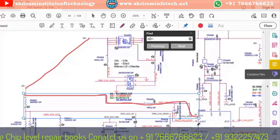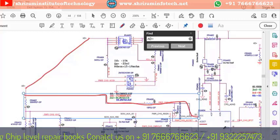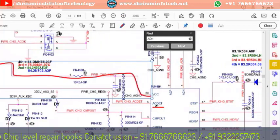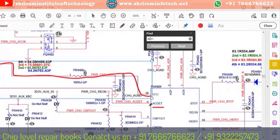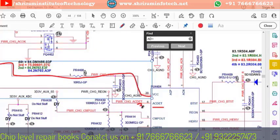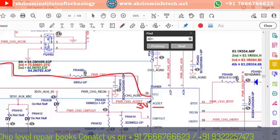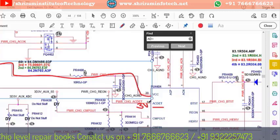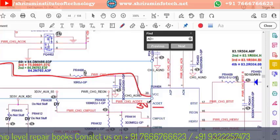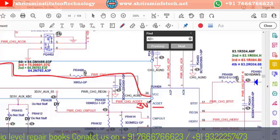Then there is one more pin which is also very important, that is called AC detect. AC detect means adapter current detect. You should get 3 volts here at pin number 6. If 3 volts is coming, that means the adapter is detected, the adapter is present. If the voltage is 0, that means the adapter voltage is absent.